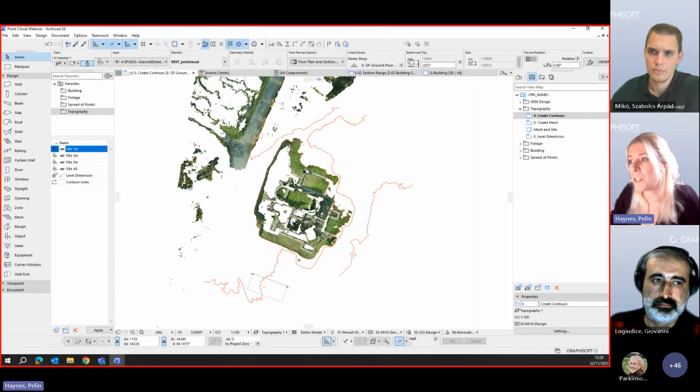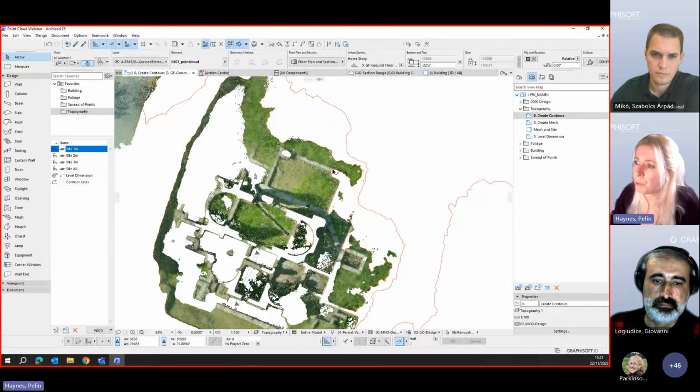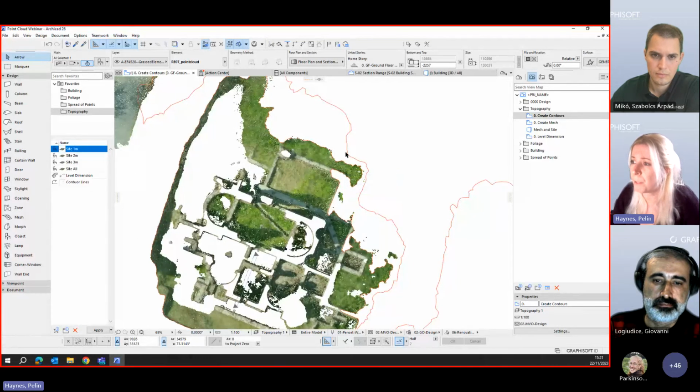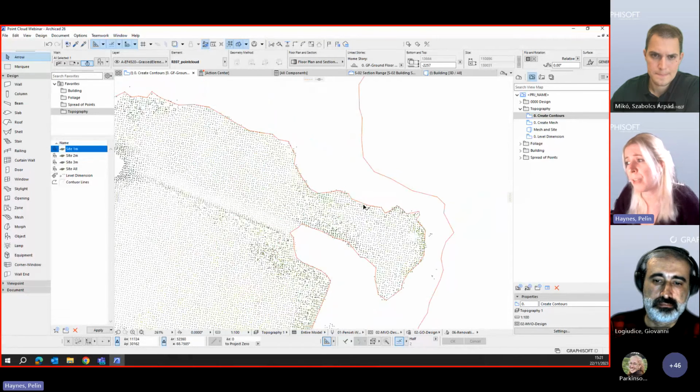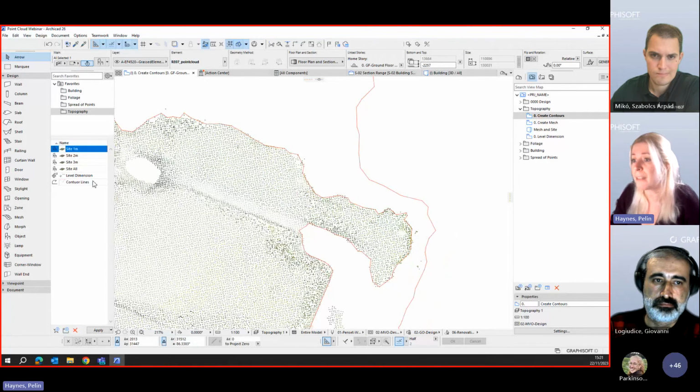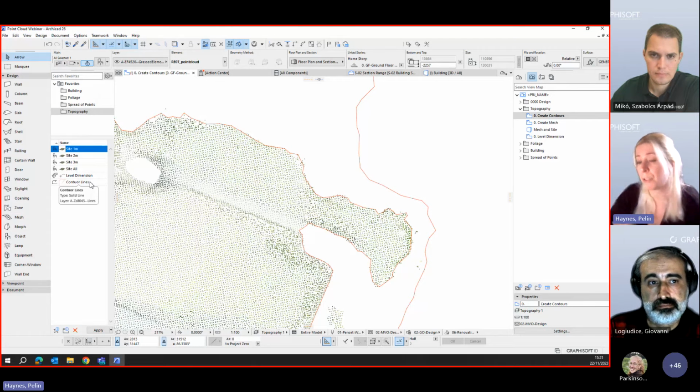Once you change your cutting plane within the object settings, part of your point cloud will still be visible. Obviously, you will lose the majority of your point cloud, but wherever it's visible, you will have a certain number of points here. You just need to trace around those. I prefer polylines in this case, but if you want to go more accurate, you could use the spline tool.